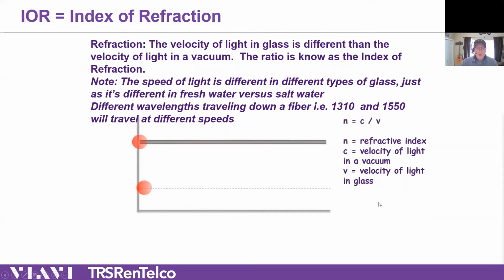So how does light work and how do we measure the distance of a fiber, right? One phenomenon that happens is light, whether that's through free space or outer space or fiber, it is a constant speed. I don't care if it's daylight or if it's, in my case, very bright daylight in the picture behind me, or if it's a radio wave from your phone, or if it's a 1310 or 1550 nanometer into your OTDR, into your fiber. They're constant speed. The speed of light is the speed of light. So we know that calculation. We know the speed of light in a vacuum, which we'll just call outer space right now, because there's no air and there's nothing to attenuate it.